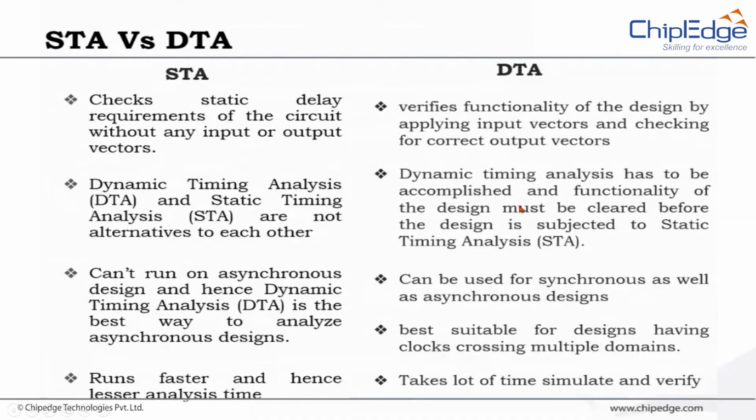And also it is very suitable for designs where multiple clock domain crossings happen. And assuming that all these clock domains are asynchronous to each other, then some kind of a dynamic timing analysis may be required for those kind of designs, focused on the boundaries. All right. So as an engineer, you need to understand and appreciate where each aspect plays a strong role and what are the gaps in each of the approaches, STA and DTA.